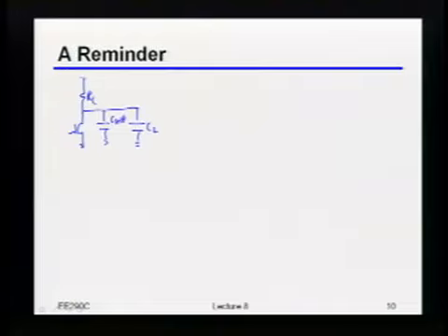Bandwidth. Bandwidth. So when you say bandwidth, do you mean just the bandwidth, or is the bandwidth times something? Gain. Yeah, it's the gain bandwidth, right? So just as a reminder, GM over the total capacitance is of course just the gain times the bandwidth, right? Okay, well, that total capacitance is of course just the self-capacitance plus the explicit load capacitance.